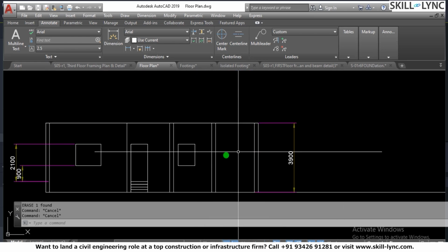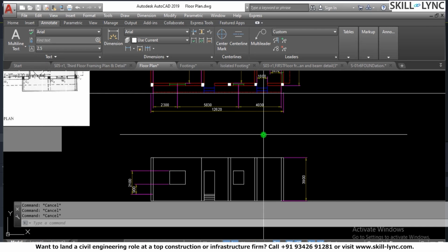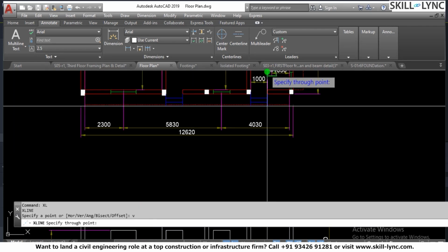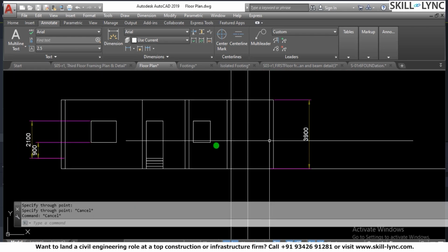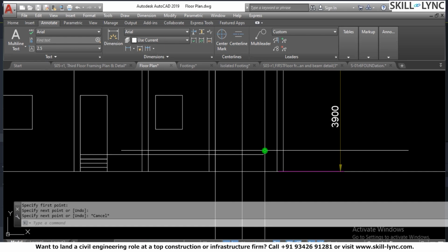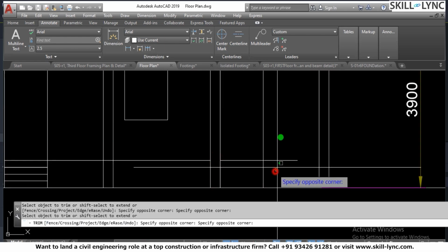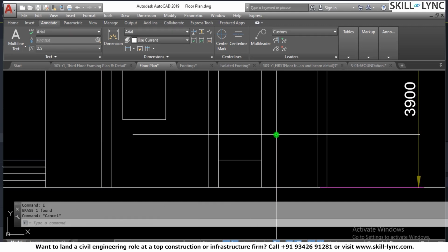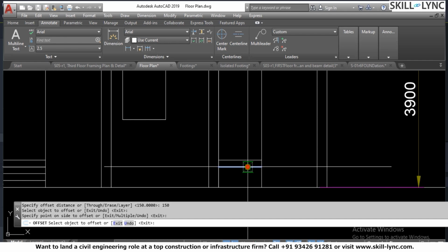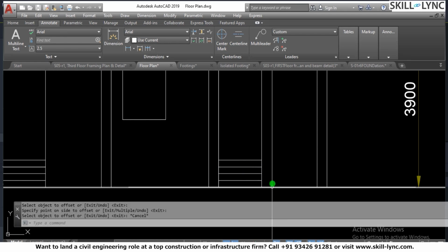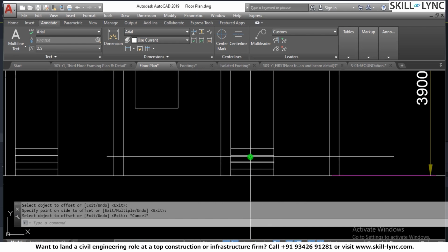So here again, now you can see the columns over here, and there's a wall here. And if you want to again get the projection of the door opening for the staircase, you can always have the projection. And let's say it starts again with this. So now something that you need to understand is the elevations are basically subjected to the design factor. So again, we have a 150 mm riser. So here in the elevation, the riser will be seen, and in the plan, the treads will be seen. Now you have 1, 2, 3, and 4 risers.